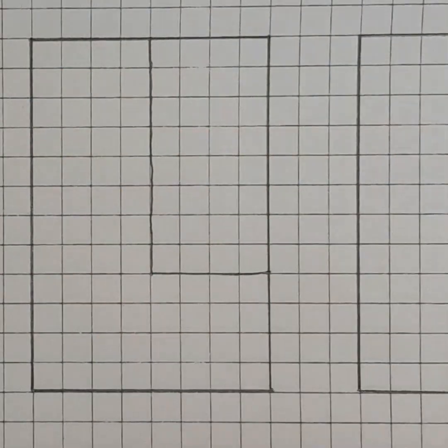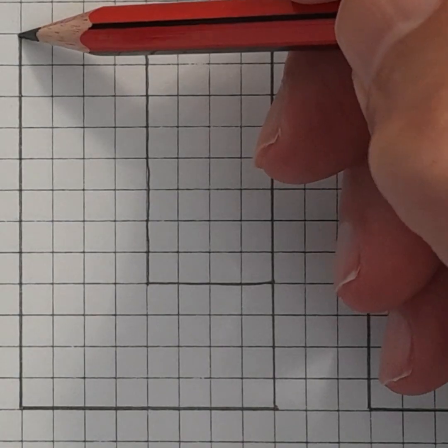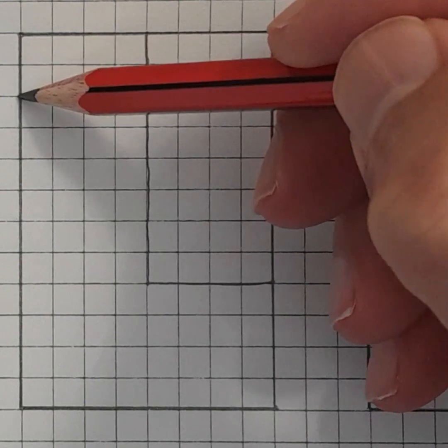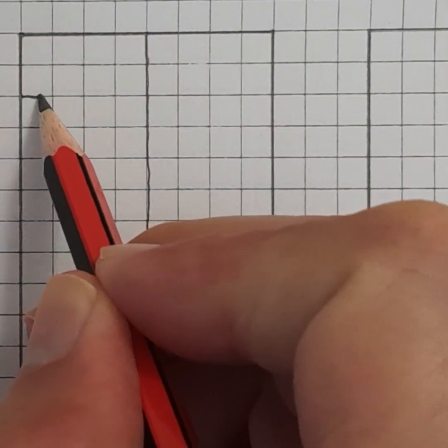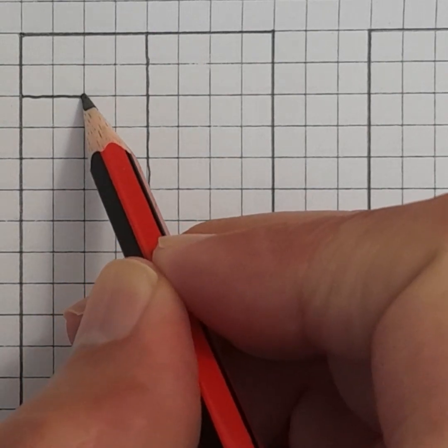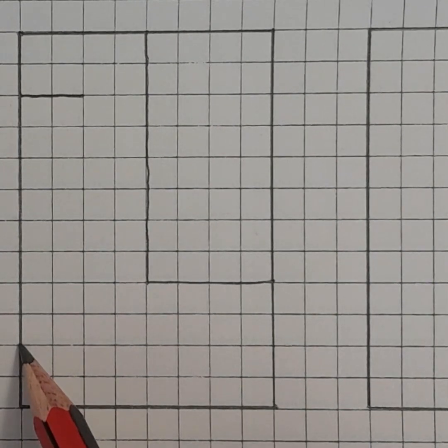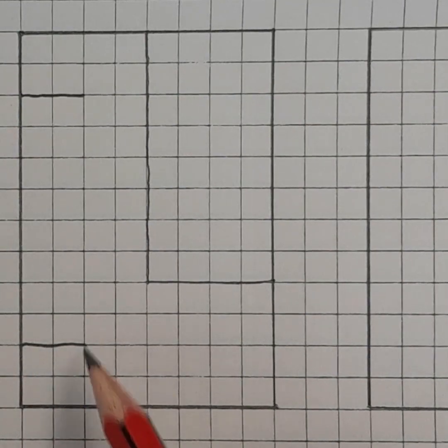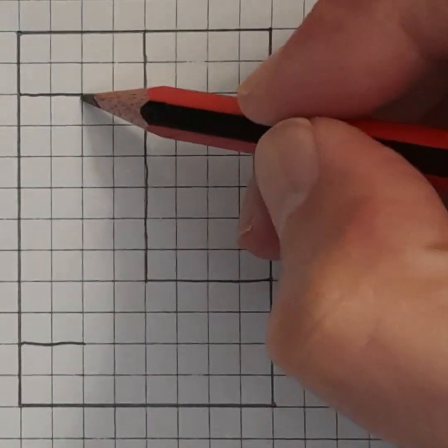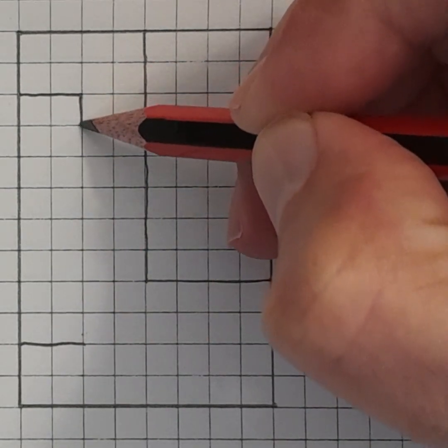For the details on the left, we have 2 lines. One from this top left corner, go down by 10 millimeter. Then draw a line to the right with length of 10 millimeters as well. Then from the lower left corner, go up 10 millimeters. Then draw another line 10 millimeter. Then connect these 2 points together with a line like this.